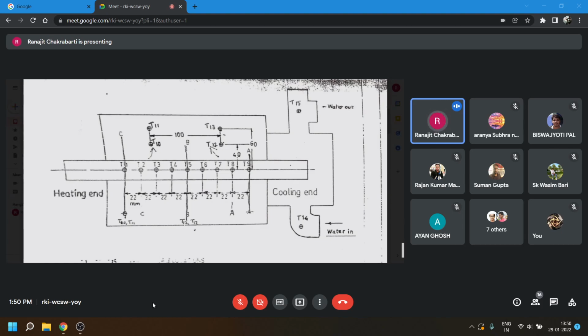We are assuming that the temperature of the rod at the surface and at the center are the same. That means temperature is the same all along this cross section. But from the surface, through the insulating powder, radial heat transfer is there. So whatever heat is lost from this point to this point, plus whatever heat is going out through this section A, if you sum the total, that must be equal to the heat which is entering through the section BB.